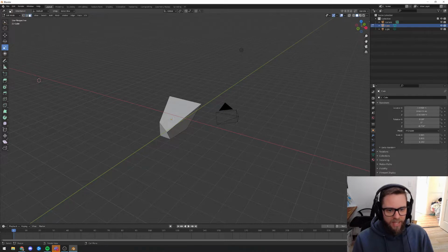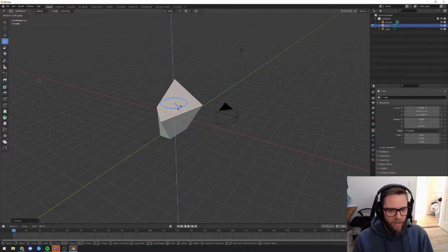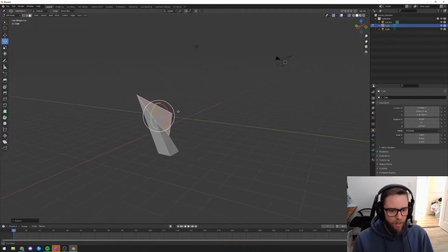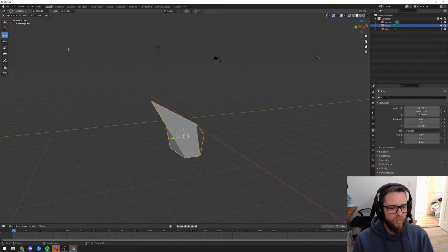The last one is face select, and I can use that to select a face and move the entire face around. Where now I'm rotating the face. So you can see how I started here as a cube. I'm going to go back out into object mode, out of edit mode, back into object mode, which by the way you can do by pressing tab on your keyboard. We'll just immediately swap from edit mode to object mode in a pretty fast way.